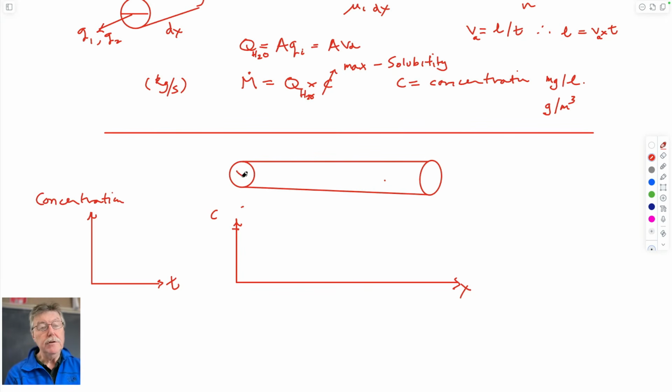So imagine that you put into here, where there's water flowing at some flow rate, Darcy flow rate, which is equivalent to an advective velocity as well. We can calculate all these. These two are the same as each other. And VA is equal to Darcy velocity over porosity.